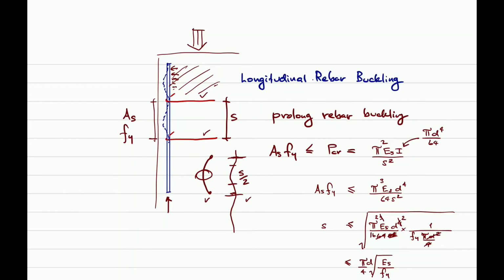No matter how much hoop reinforcement you add in, when concrete bursts out, you have two phenomena. First, concrete itself produces the pressure, and second, the hoop breakage is also expected, right?